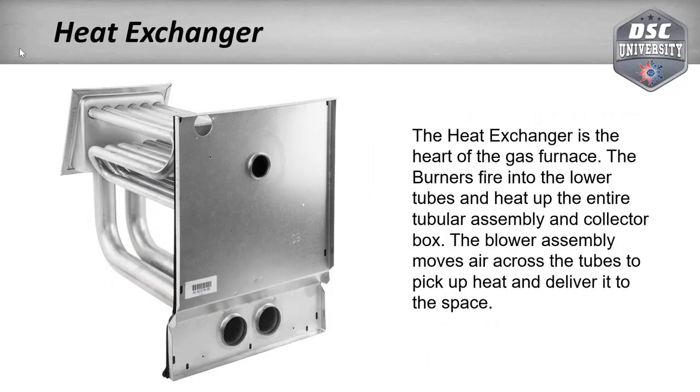So once our burners light, the flame coming off the burners goes into these bottom tubes on the heat exchanger. The way it works, the flame comes in through these bottom holes, through these tubes up here to a collector box, and then back and forth through these tubes, and then our inducer is mounted here, which is pulling air through the entire assembly. So as all these tubes heat up, our blower assembly is then going to blow air across those tubes, which have heated up now, and carry that heat into the house.